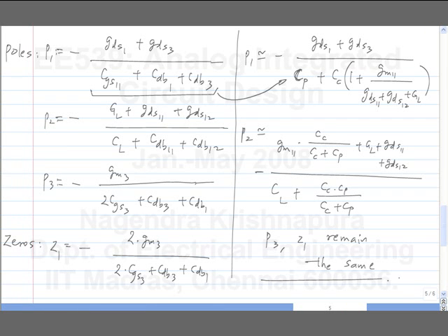So we have moved P1 to lower frequencies and P2 to higher frequencies. So we can compensate it. What is the unity gain frequency? As I mentioned before, the op-amp is usually specified by the unity gain frequency and the higher poles, and the DC gain. Equivalently, you could specify the lower frequency pole, the dominant pole, but that's generally not done because what appears in the expressions when you put the op-amp in feedback is the unity gain frequency.